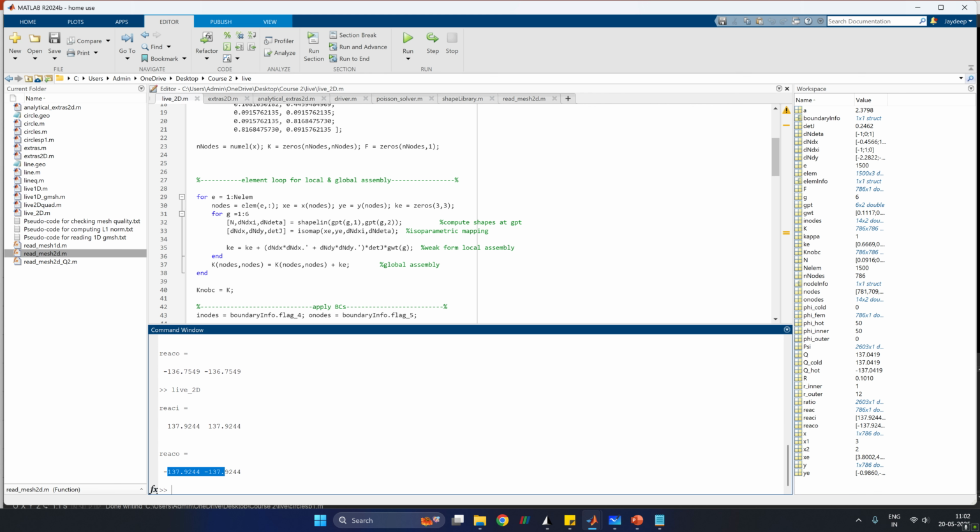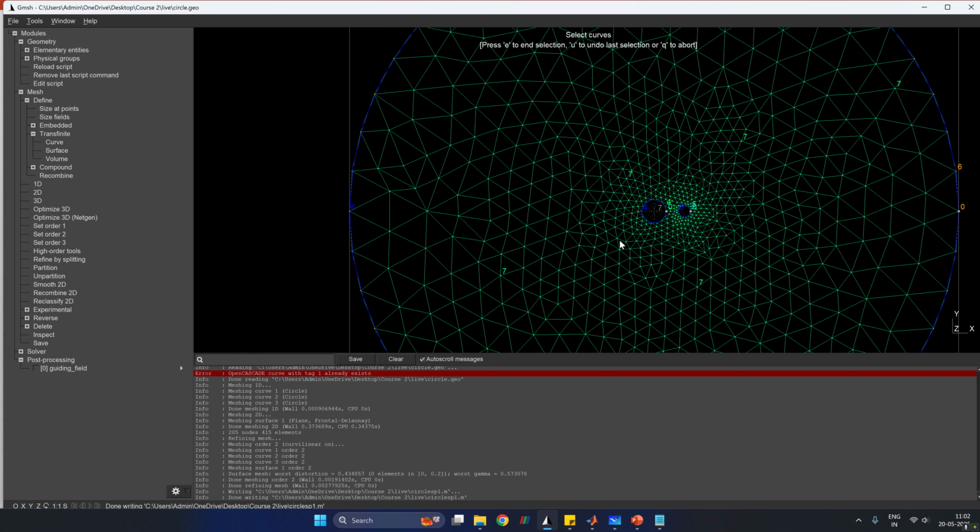This is really misleading, because you can get misled by being close to 137, but really you are using a coarse mesh, and a coarse mesh is not accurate. So it's important to do the grid convergence study and get an asymptotically convergent value for the radius which you are using.